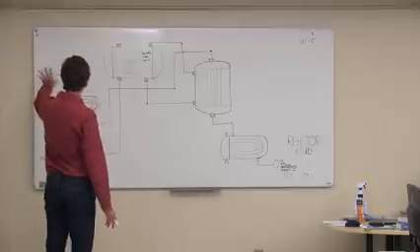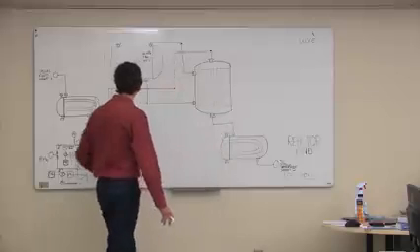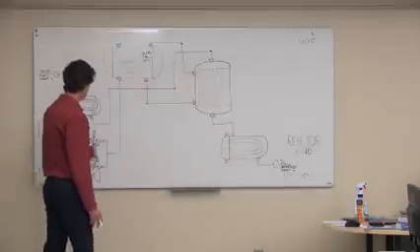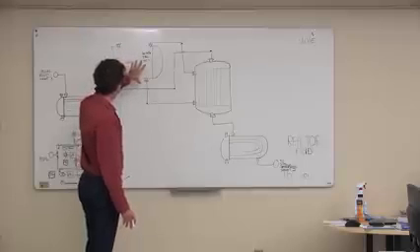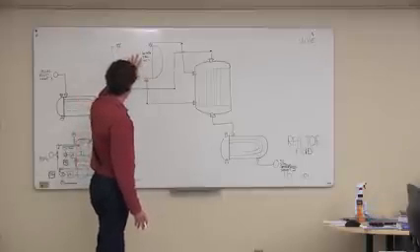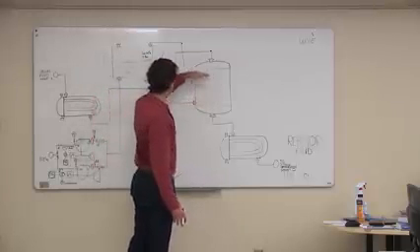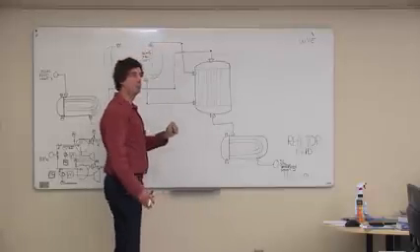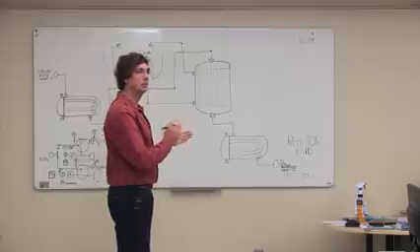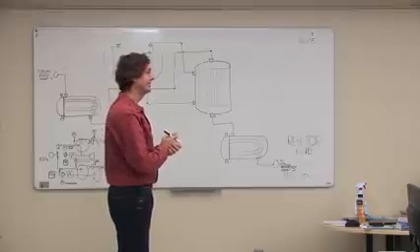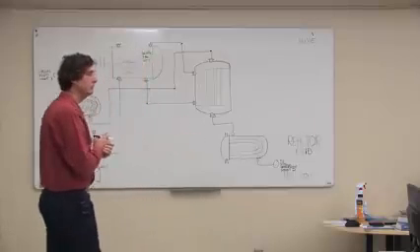Okay, so that's the syngas coming through, cooled through the reactor, through the heat exchanger, and away. We've got our boiler feed water coming in. It's coming into the steam drum here. It's mixing with the returning water, coming down, being boiled through the reactor, back through here. What are we missing? Are we missing any major lines?